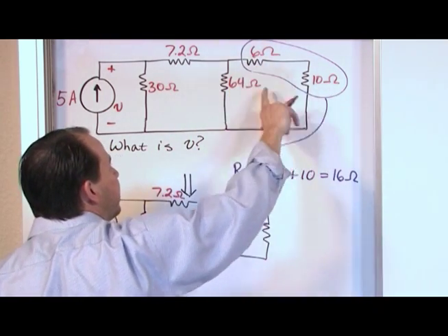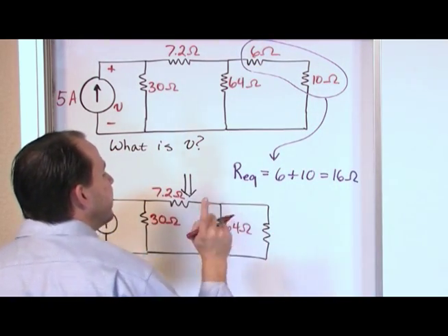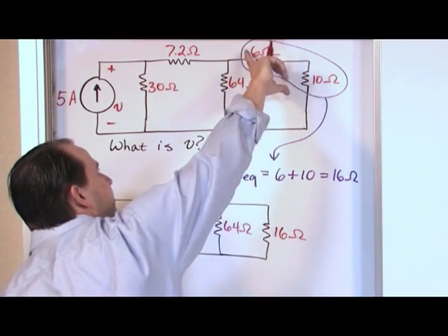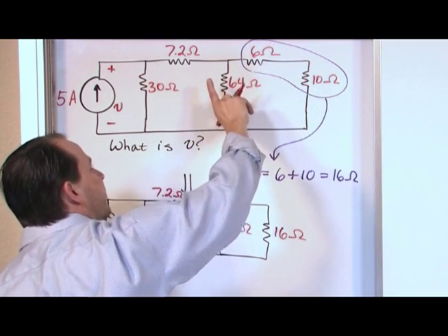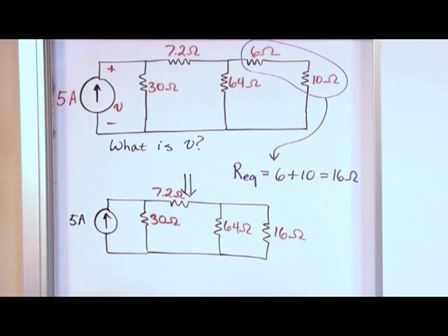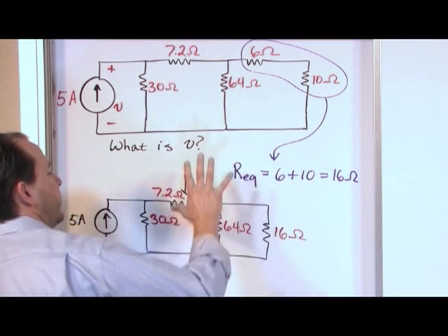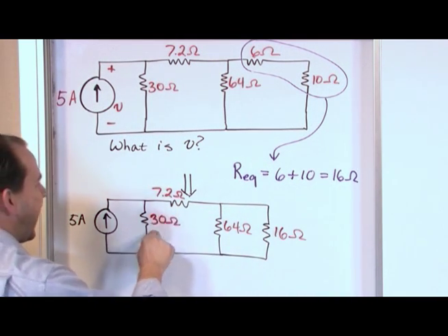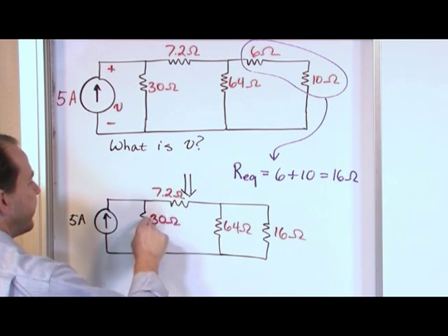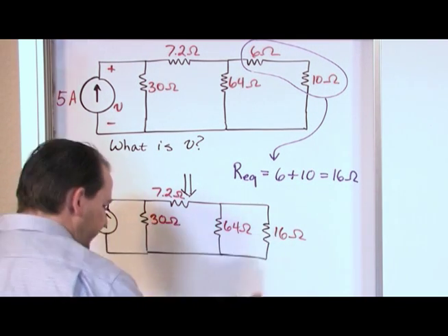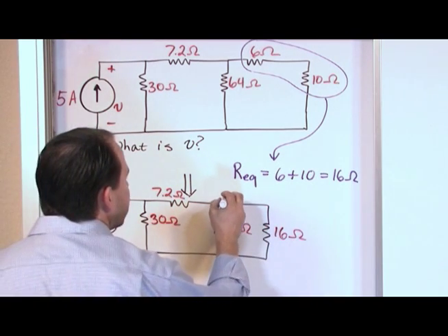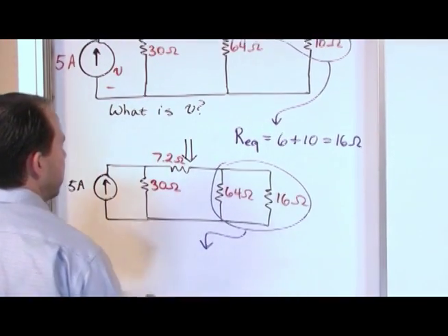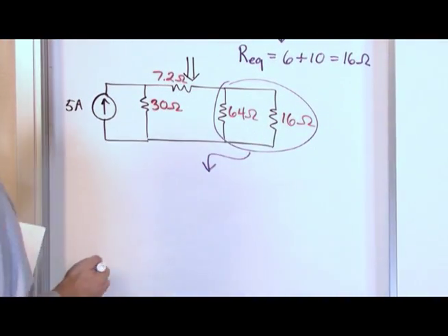We've just simplified this. So the final resistor we have is in parallel with this guy right here, because what we've simplified is still connected across the terminals of this resistor, so it's in parallel. So now we stop looking at this circuit, we look down here and ask, what can we do next? You can't really add this to anything because they're not in series. There's branching going on here. But these two guys are in parallel. So get your pencil out, draw a nice little circle here and write a little note to yourself right there to tell you or your professor what's going on.